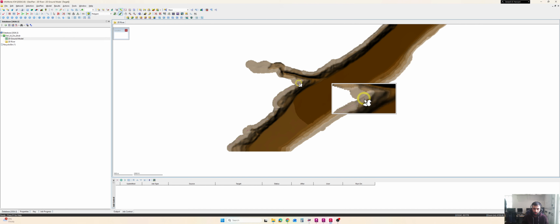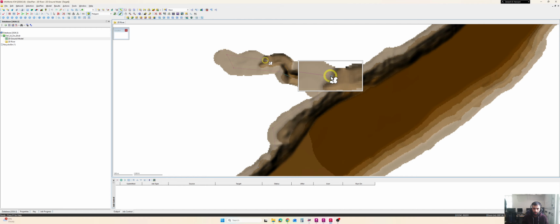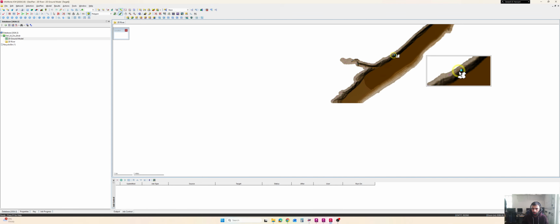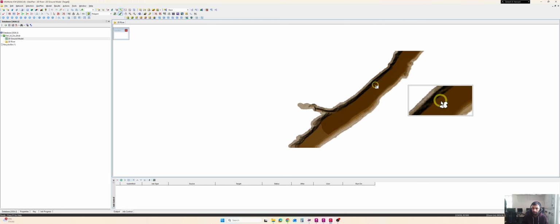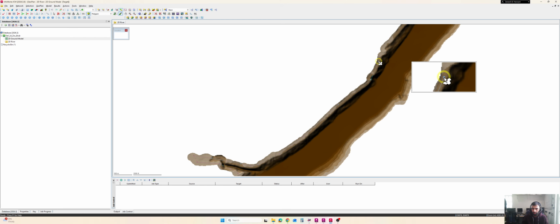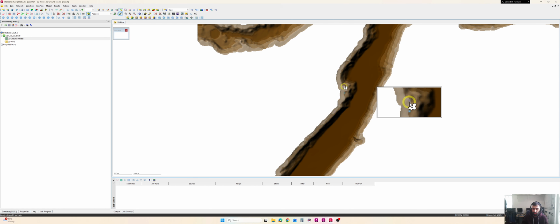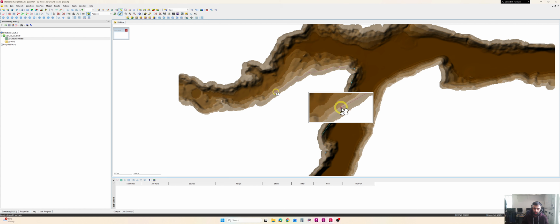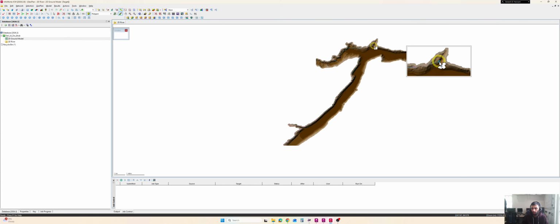So you don't need to go outside the ground model. You have to be very careful and keep within the ground model that we have imported. This will help us to create the 2D zone. So this is a big site, so to show you, I will just quickly close this one. So this is how we create the 2D zone for our river section. I was just skipping some of the parts because my main purpose is to show how we can create it.